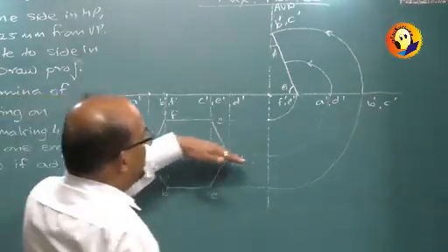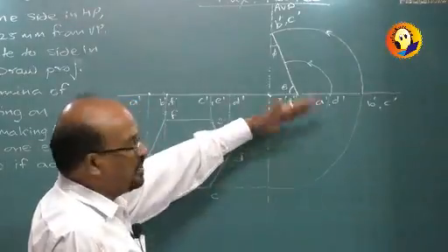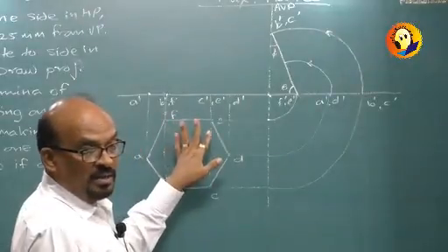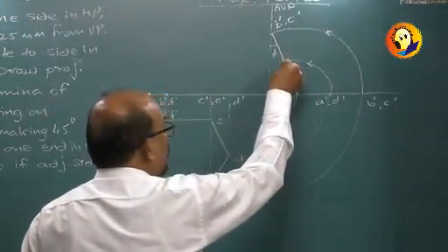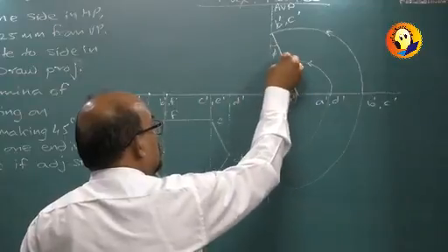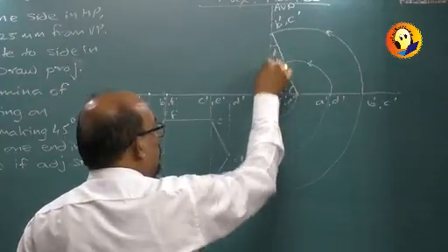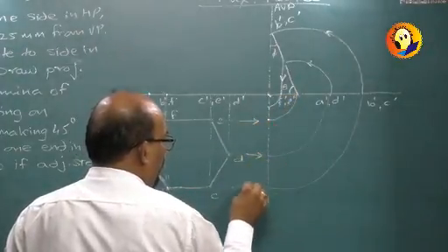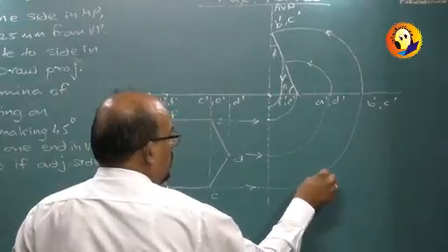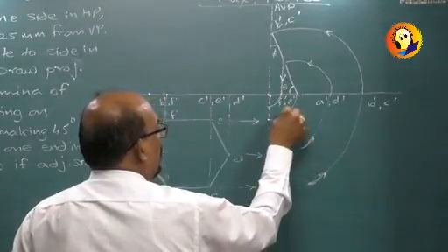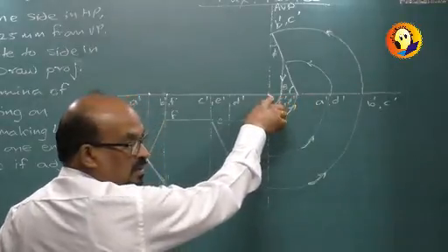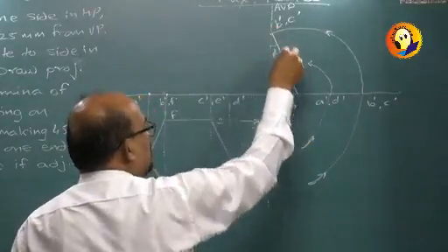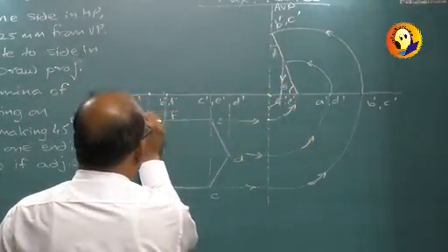Now rotation in one view. Now where is the rotation? It is the rotation in the front view actually. So movement parallel to XY in the other. So I will have to take these points down. See the procedure. I will have to take these 2 points down and rotate them back. See, here I have taken them to the side view. So this was the rotation that I had, and this was the center. Then I have rotated about F dash, E dash, so this is my next center. After rotation I got the points. Now I am coming back and going here.